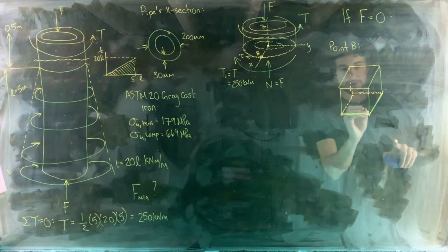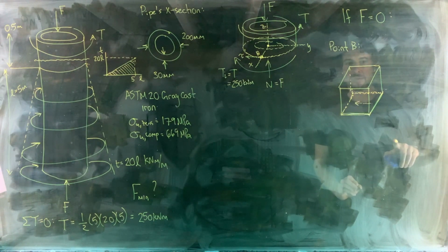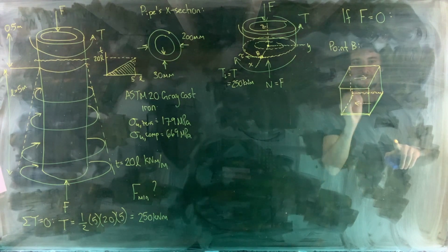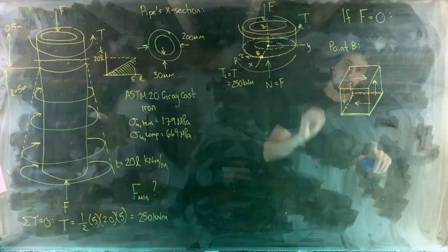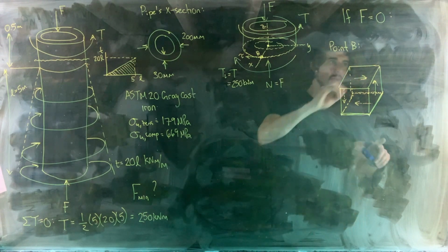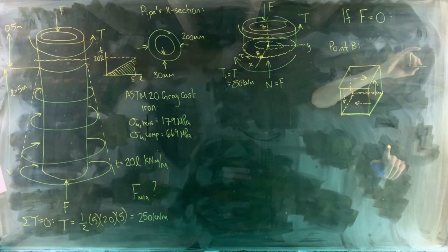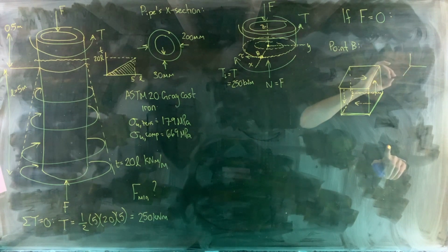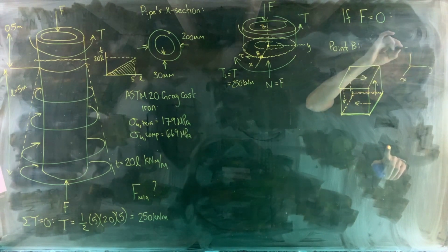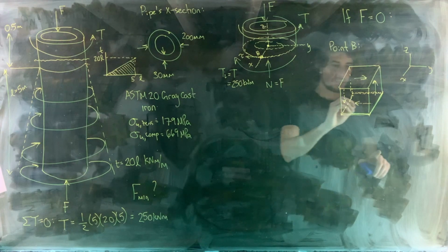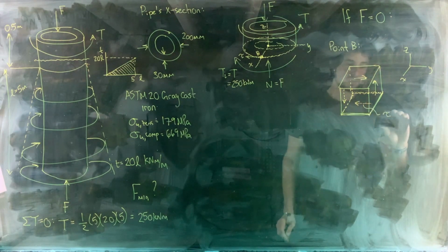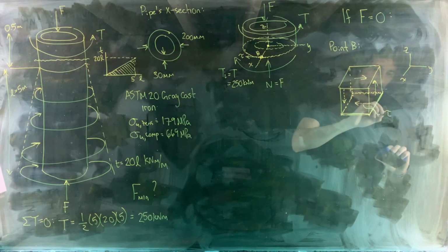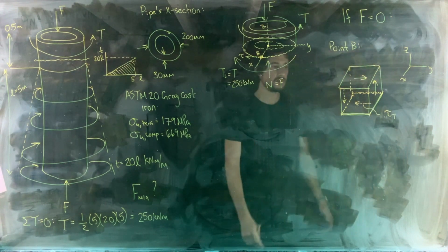There's tau. So on our element, that's a shear stress like that on the bottom surface. And then top surface shear stress like that. There we've got another one, and there we've got another one. Let's put our axes beside. So we said we'd have X, Y, Z there. So here we've got our shear stress, tau. In this case, tau due to our internal torque T.